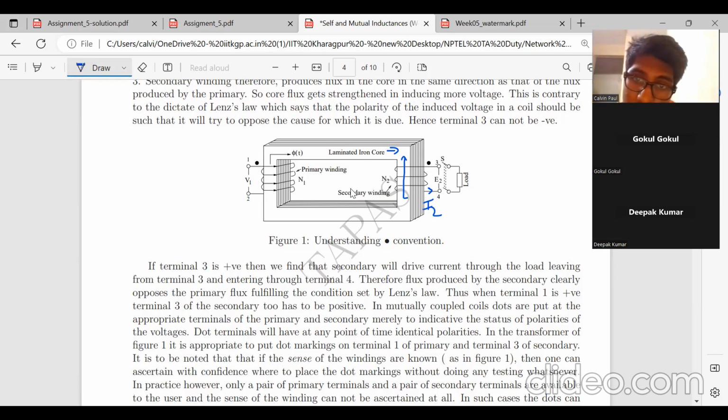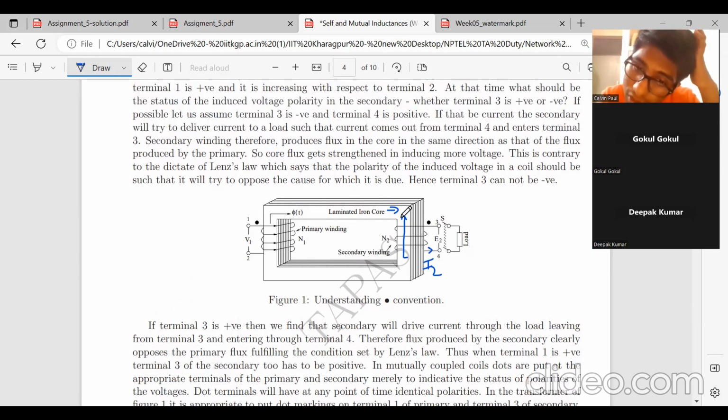that the current. So if we want the flux to be generated like this, according to the right hand rule, the flux which is generated depends on the direction of the current. This is my right hand. So these four fingers denote the direction of the current. If the current is flowing in this direction, like this, then the flux which is generated will go to the top. But in case the current was flowing like this, then the flux will go in the bottom direction. Now what we want is that the flux should go up. So for the flux to go up, the current should flow like this, right? So that's why.